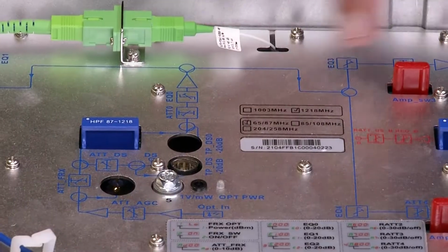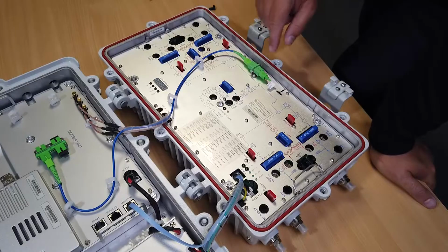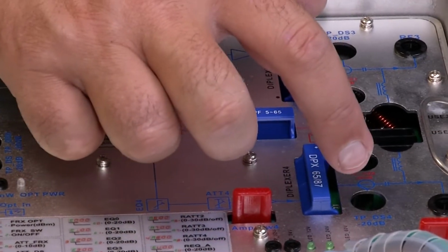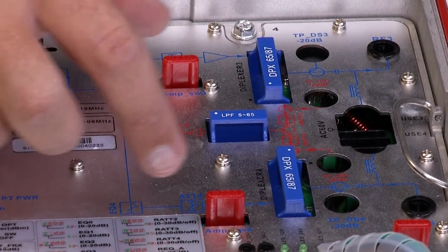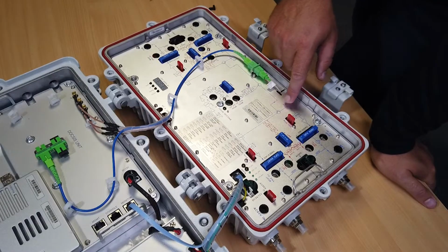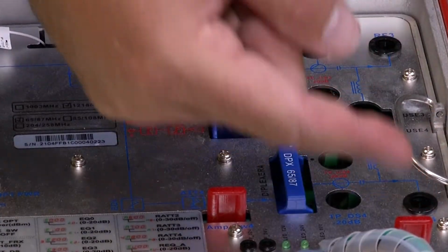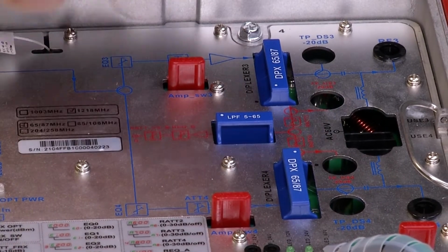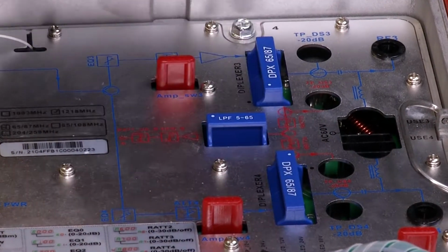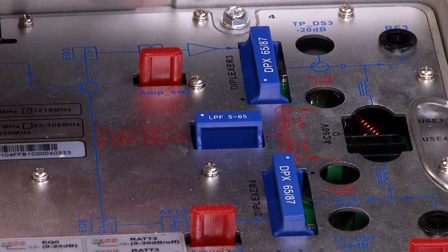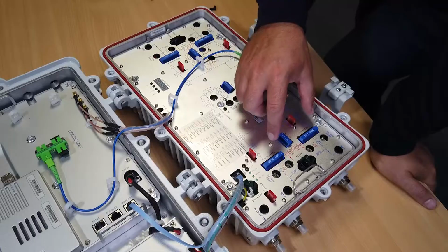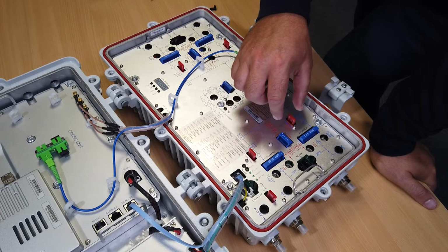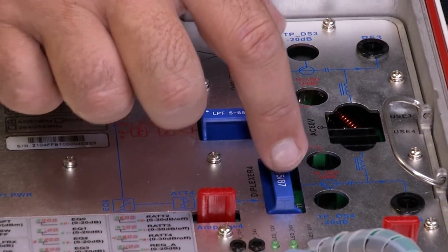Again, on the schematic, you can see how the downstream is split into left and right. After this split, the upstream is again split into two directions, once again to the left and right halves. But it's the same upstream module for one of each of them. You have another option here, to put a 30 dB attenuator on any output, to attenuate it remotely by using JM Data Admin or the web interface of the DOCSIS node. This attenuation only works on upstream, allowing you to trace upstream faults.